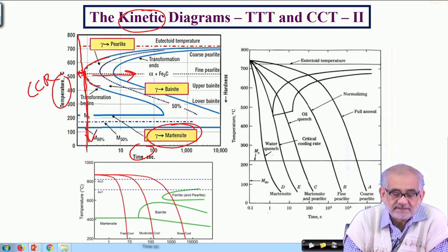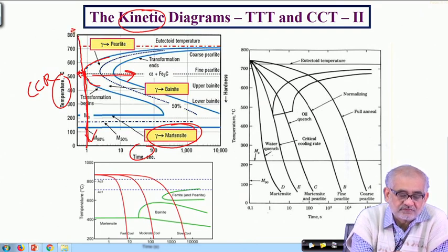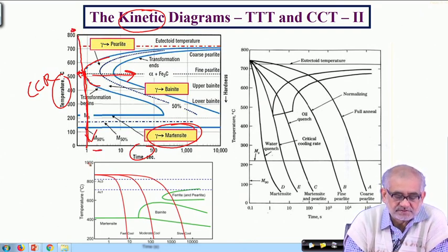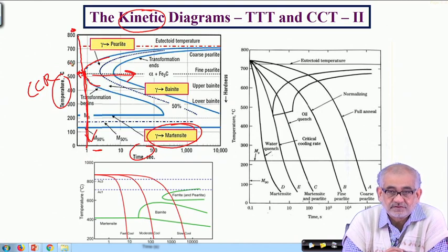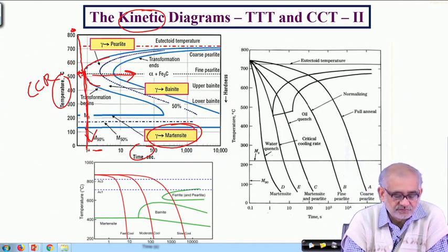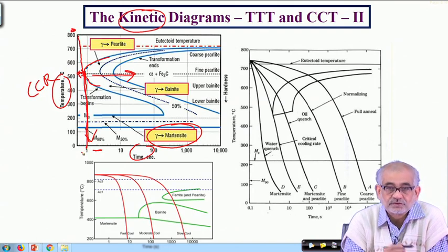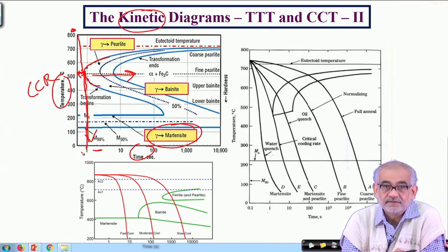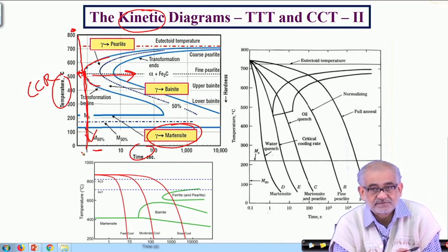easily. And if I cool slow, the advantage is that I incur less or least amount of thermal shock, because I'm cooling all the way from above 800 to room temperature. So this 800 degree gradient is large if we need to cool within a few seconds or less than a second. So the cooling rate we are talking about is actually a few hundred centigrade per second.